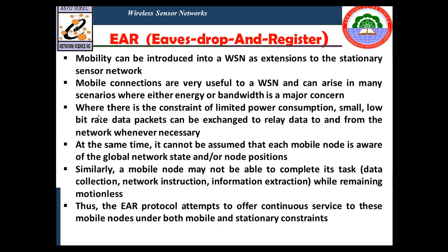This is sent by the stationary node in response to the MI message, the mobile invite message, and indicates the acceptance of the MI request, which causes the stationary node to select slots along the TDMA frame for communication, and the stationary node will enter the mobile node in its own registry. Mobile disconnect: with this message, the mobile node informs the stationary node about the disconnection, and for energy saving purposes, no response is needed from the stationary node.